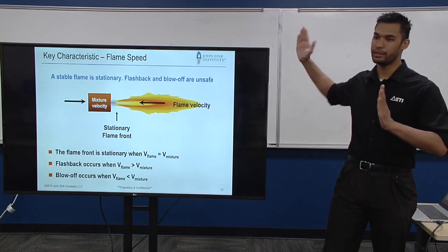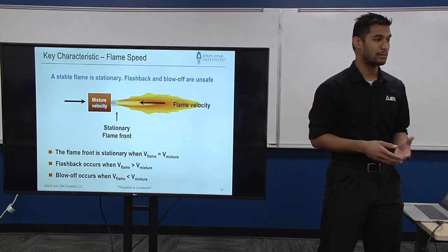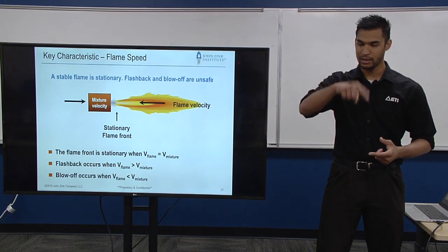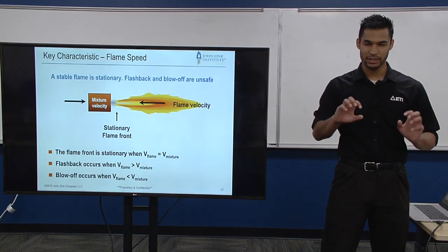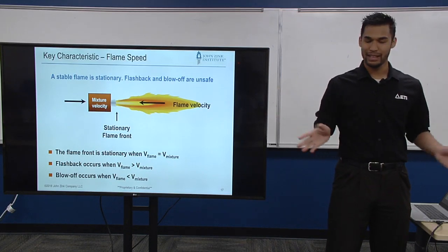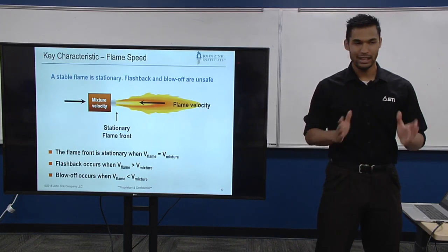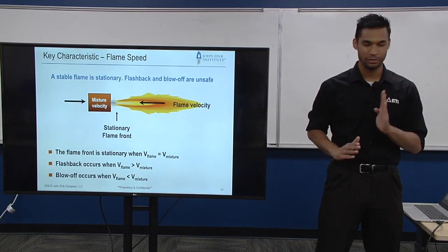We don't want the thing moving out and in and out and in, because if you create a resonance, it could easily become unstable, right? If you have something that's really odd and harmonic, and someone walks by the heater and sneezes, that could throw off the entire resonance, and then all of a sudden you're no longer stable. So you've got to make sure you hold a stationary flame front.